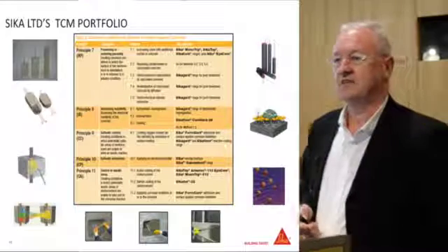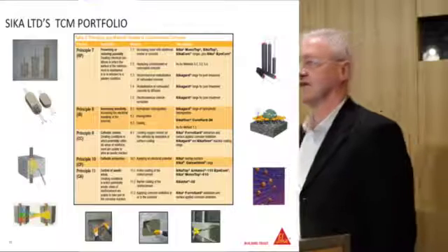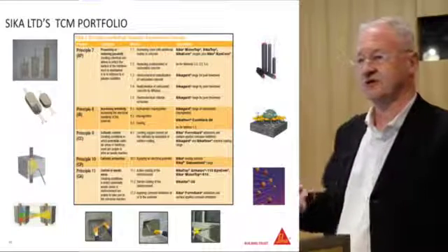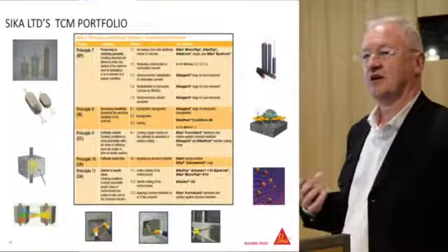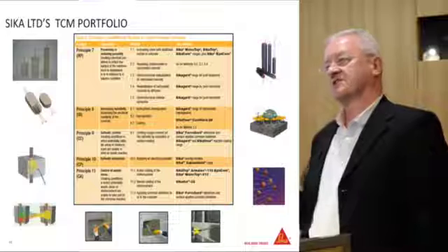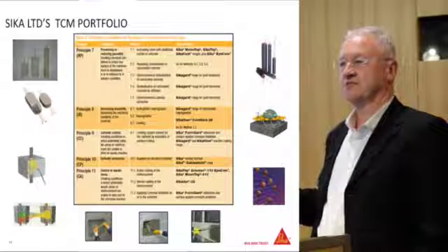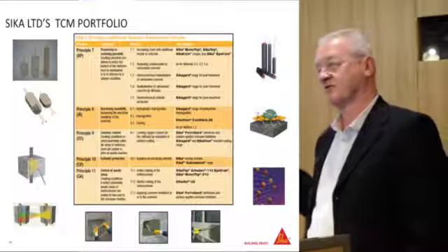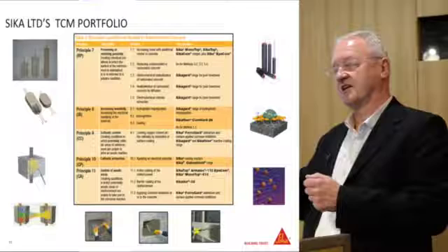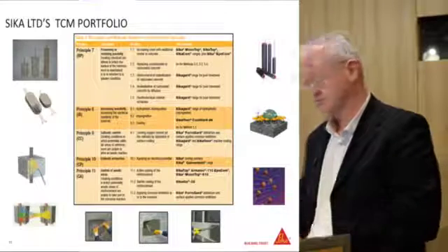We've got the galvanic anodes as well, in different sizes depending on the level of chlorides, and also on possible corrosion rates that you've identified, which will determine which one you actually use. And then we have inhibitors. Surface applied inhibitors, or vapor phase inhibitors, where if you've got the problem of corrosion fairly deep down, we can drill into the concrete, apply the inhibitors and they'll spread through the capillaries of the concrete.